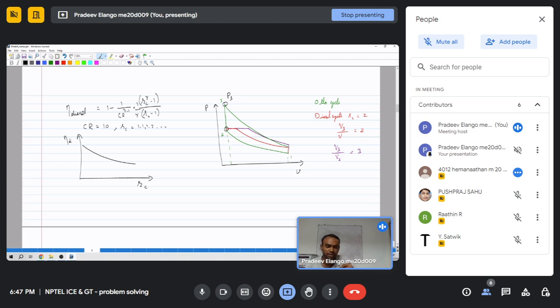And now from this very high pressure, I am expanding till say 4, and then coming to 1. So because of this, the area under the curve, which is the work done, is very high, right? Work done for the Otto cycle, I got a very high value.